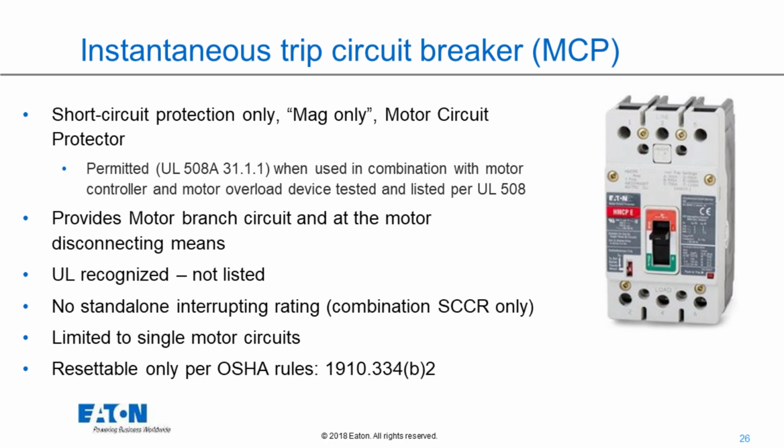Doesn't have a standalone interrupting rating. It has a combination rating with whatever controller it's downstream of that it's protecting. Limited to single motor circuits. Same resettable OSHA rules apply.